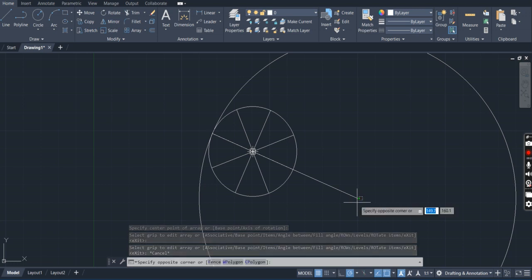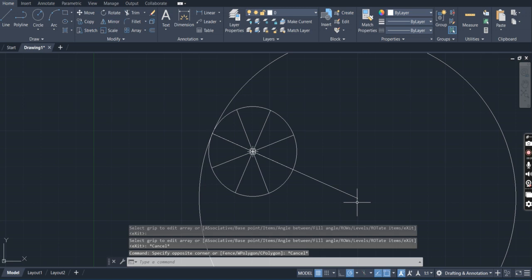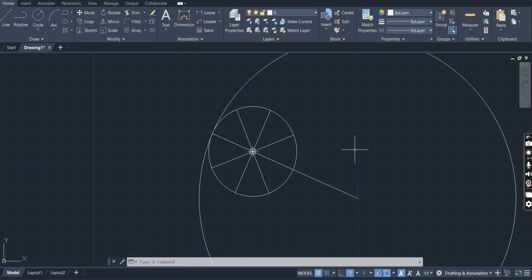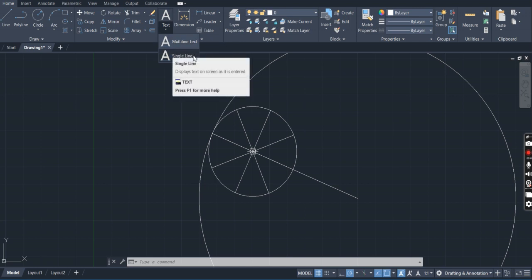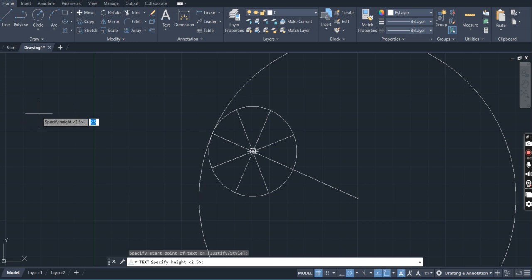Now this is the center point O. We have to indicate all the points, and before that, calculate the angle, how much the circle rotates, how much distance it should cover, how much angle it should cover. I'm going to use single text. It can be calculated using one relation: 360 times the radius of the circle, that is 25 mm, divided by the radius of the bigger circle, that is 90 mm. Then enter, that equals 100 degrees.